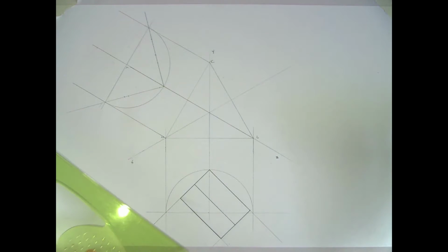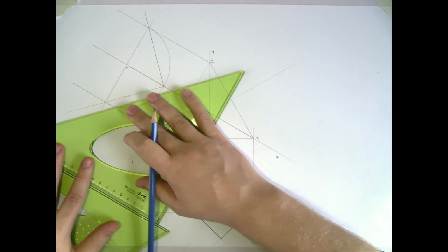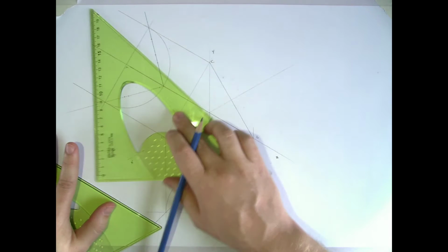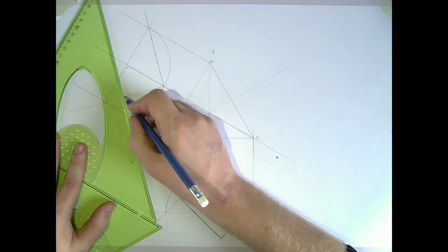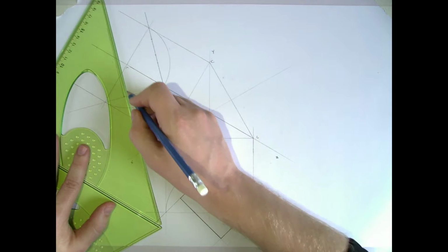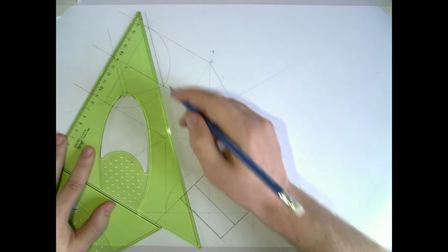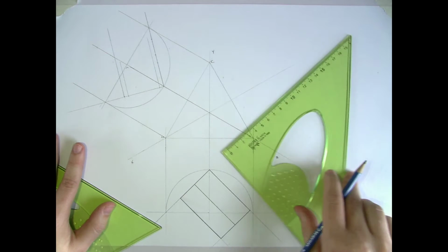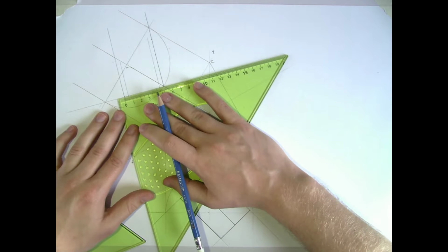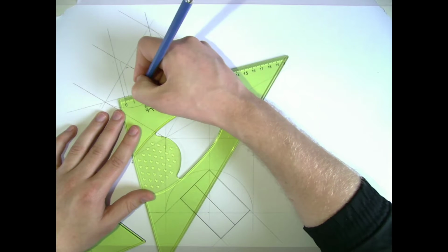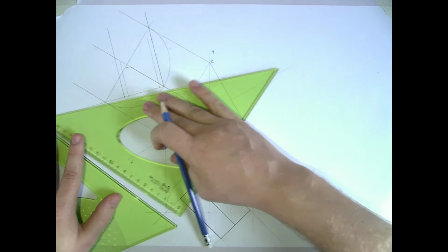So I'd like to put all of these heights in first, and then it's a bit easier when I'm using my sliding set squares to get the lines that I'm looking for. So this is the very outside of it. This line in here is part of the door for the kennel. One other point that I should have marked on this is the center point for the ridge. So that's going to be 25 mil because it's half of the 50.